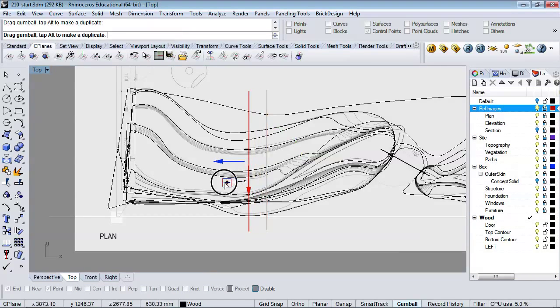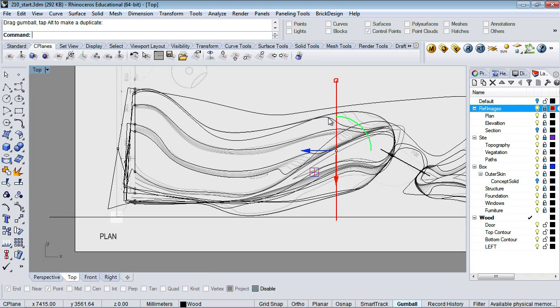move this and I can describe this curve, but one thing that sometimes is helpful when you're doing these sweeps on rails is to think about tangency. So here it's okay, this is kind of perpendicular. But if I go over here, you see this line where it starts to drop back. Sometimes those cause some weird things because the curve is trying to navigate along that curve, and if you create a curve where it's already offset, so it's not in tangency to it, it's going to take that curve and kind of do weird railroads, and sometimes that can give pinch points or strange geometry.